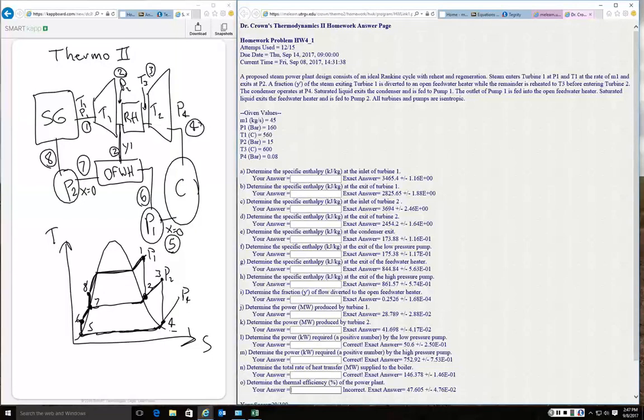So I've got two isentropic processes. So we think through how are we going to find the different values that we need. Of course, I want enthalpies across the turbines to get my work. I want the enthalpy change across the pumps to get the power or work for the pumps. And then I have the steam generator. I want a delta H across the steam generator and a delta H across the reheat. Some of those H's are used for two different delta H calculations.